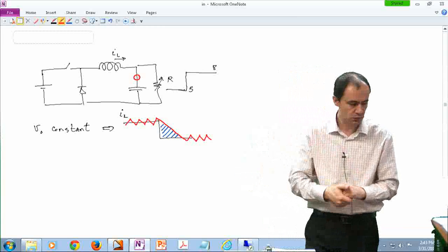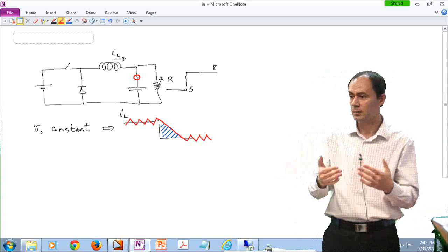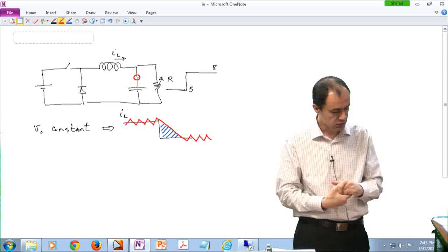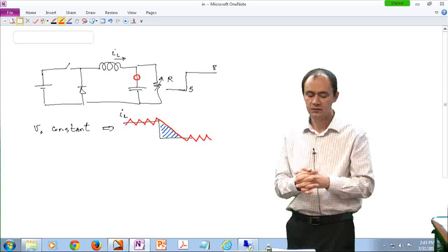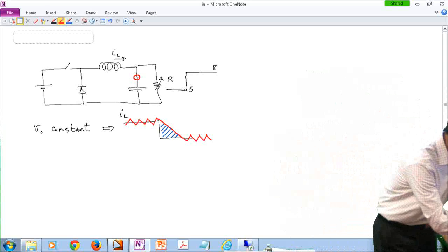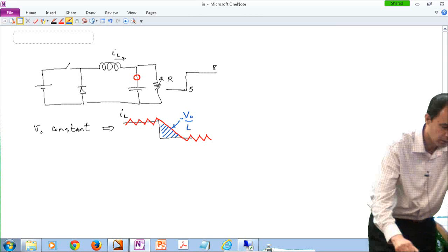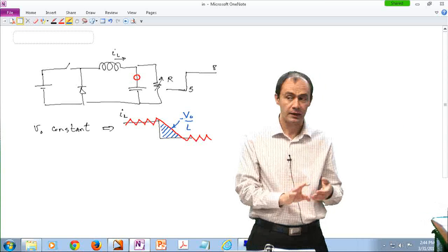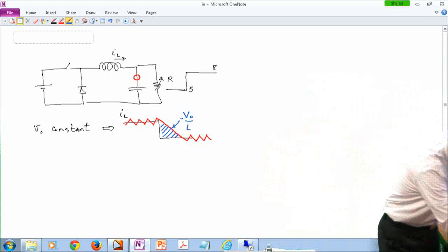So you have a voltage compensation network. The output of that voltage compensation network is always almost 0, and the capacitor current should follow that. That system behaves a little bit faster. There are other techniques, for instance, somehow manipulate the value of the inductor, and if you observe a transition, remember this slope is V out over L. So if during the transition I manipulate the value of the inductor and make it smaller, this slope is more steep. Therefore, you will have something like this, for instance.